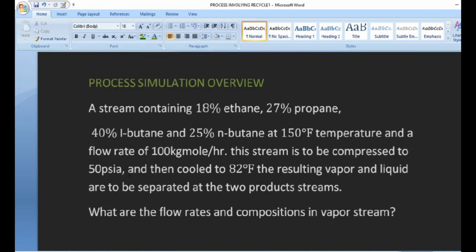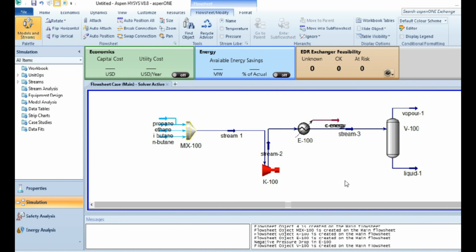In the case of today's class, I'm going to show you how to overview a process simulation. Let's assume you are trying to see the temperature throughout the whole simulation. Maybe you are trying to see whether you made a mistake, or you have a doubt, or you are not satisfied with what you have obtained at the output. So just go to the flowsheet here, and in the case of 9, just click temperature.